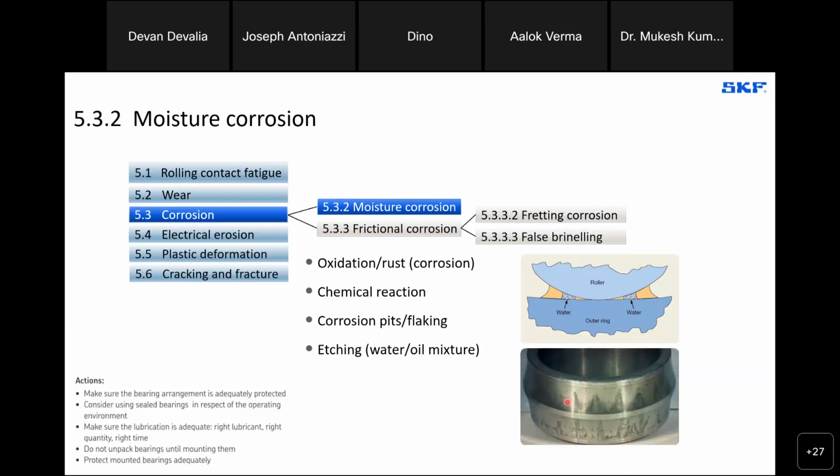And as the bearing starts to run again, these grayish black areas might get rubbed somewhat and lighten. So sometimes it is a challenge to determine that moisture was the initial cause for some of the damage that you'll see, because these spots become areas where spalling and flaking initiate and then spread. And you imagine then you will get abrasive wear and surface initiated fatigue and everything else layered all over that.